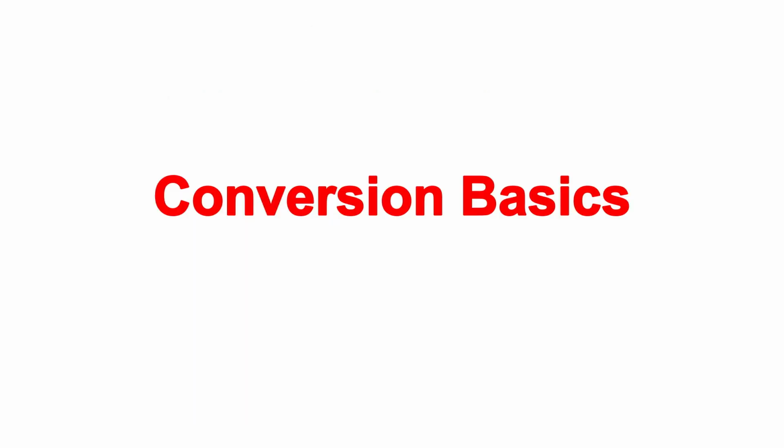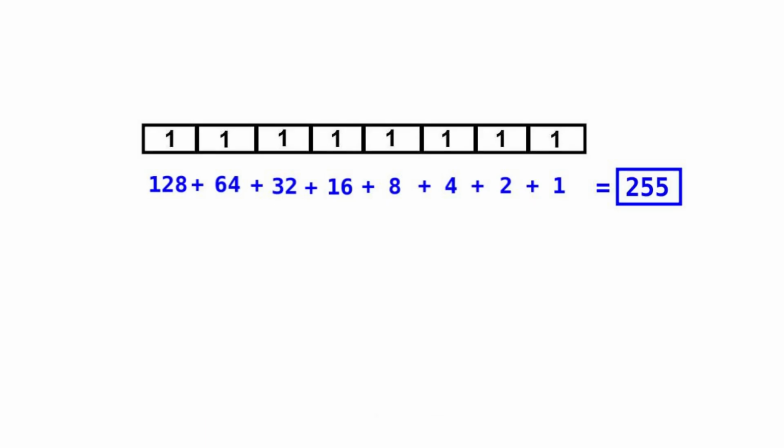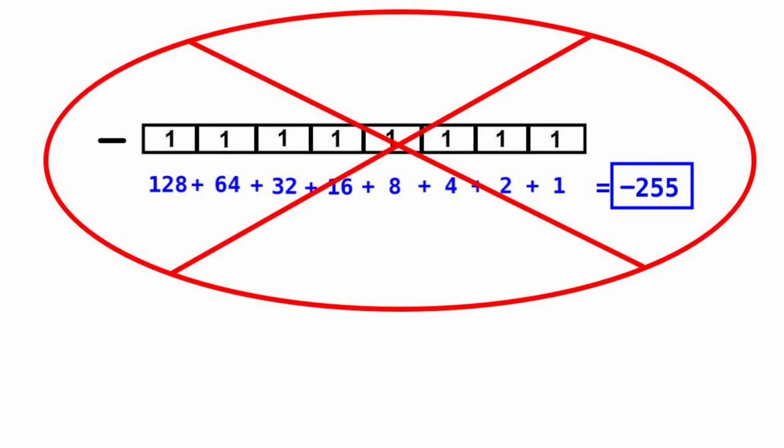So positive integers and characters are easy enough, but sending and receiving negative numbers is a bit trickier because we don't have the benefit of just putting a minus sign before the value. The secret is to use something called 2's complement.